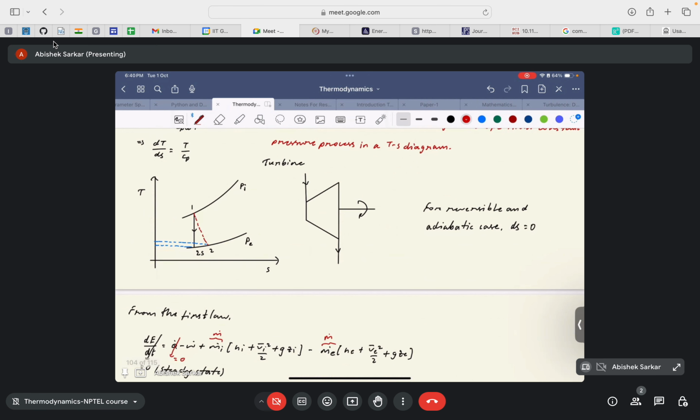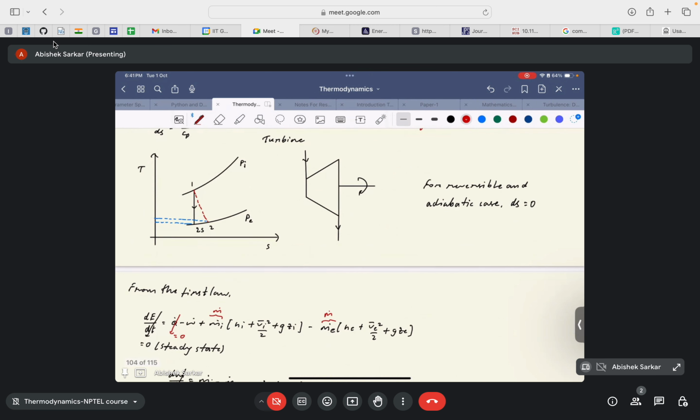Simple. So as we know, turbine is basically a thermodynamic system used to expand the hot vapor or steam and obtain energy by rotating the shaft. Okay, they use the steam and vapor to rotate the turbines and produce energy. Okay, so since there is an expansion, it will imply that the pressure of the steam will go down. Okay, steam or the vapor or any working fluid that is being considered will go down.